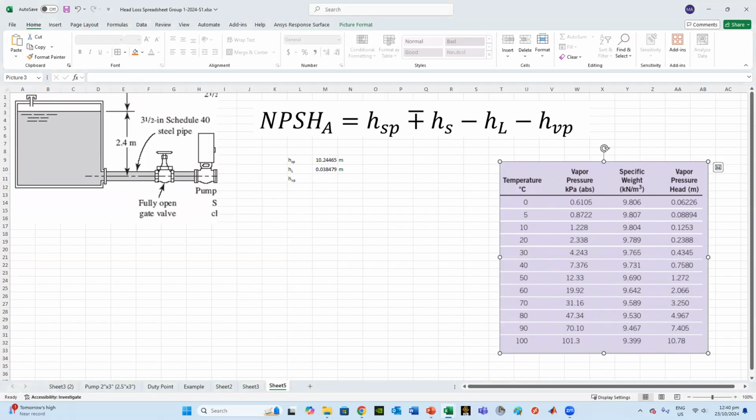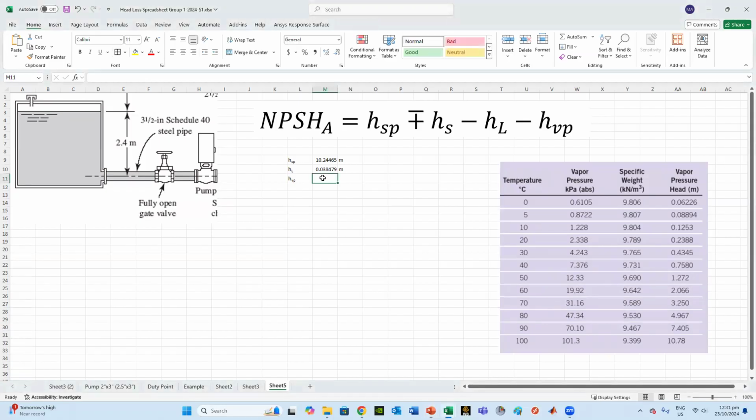That's where required some type of interpolation because we don't have that value. There is another option if you don't have that table. Technically you can select that, doing it with respect to selecting different values from it. So either table 13.2 and you do some interpolation, or you go through it. So after interpolation, this value will be close to 0.18, and that would be in meters as well. So interpolation for it.